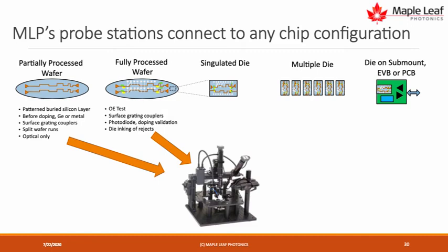Some folks, by the way, find it helpful to take a partially processed wafer and then just change the metallization for a subsequent test or subsequent processing to hook up different devices. For example, they may have enough electrical probes, bond pads for only, say, 1,000 devices, but they'll put 4,000 on the wafer. And what they'll do is make a measurement of the passive devices to make sure they know which set of 1,000 to hook up. That requires a lot of agility on the part of the project team, but it's a way of getting a lot of insight and being adaptable to the variations that come from the fab.